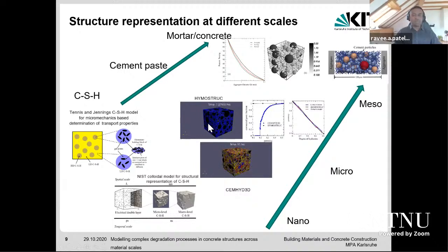However, they are completely different in terms of representation of pore structure. For instance, in one model, you can have complete depercolation of large pores, and in other models, you can always have large pores connected. So you have pores ranging from a few hundred nanometers always connected, whereas in one case, it gets disconnected completely. And this can lead to different properties and behavior. So it's very interesting to test both these models, and this is what I normally do in my research.